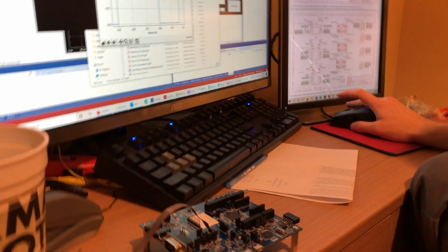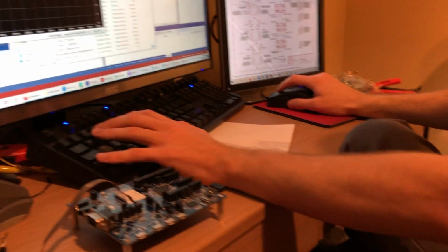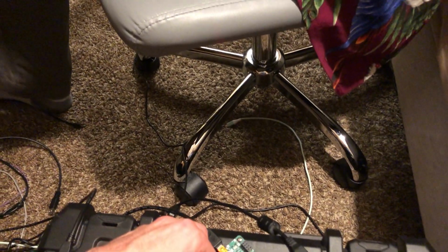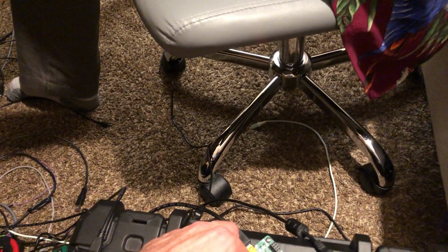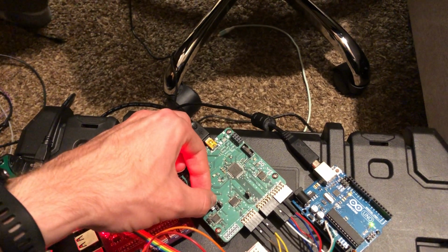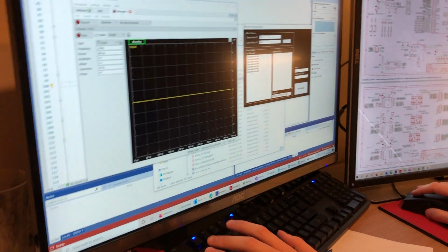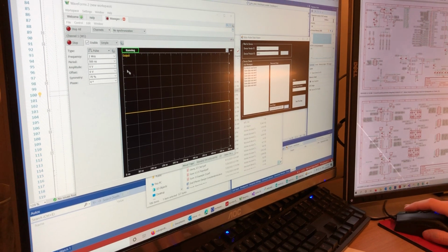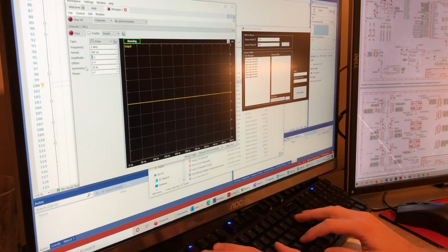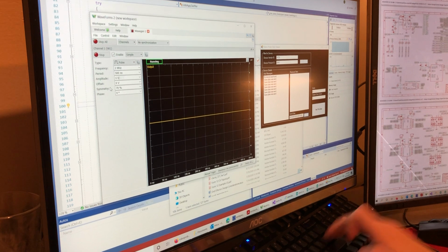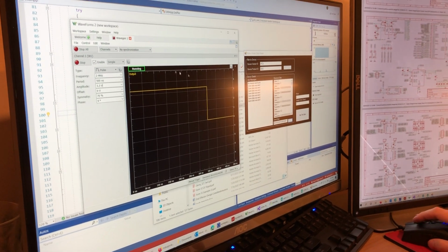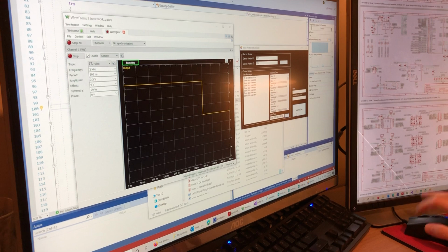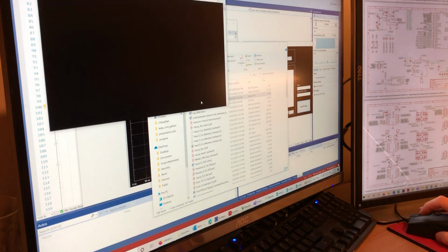So next, we're going to show you that this same functionality also works at the 1.8 and 3.3 volt logic. Which one do you want to do? I'll do 3.3, or we'll go in order. It doesn't really matter. All right, so we are now on 3.3 volt mode. And once again, we can send a command to the Robo probe to start sampling on the next rising edge, and then we can start a 3.3 volt square wave, and we can send the data to our plotting utility.